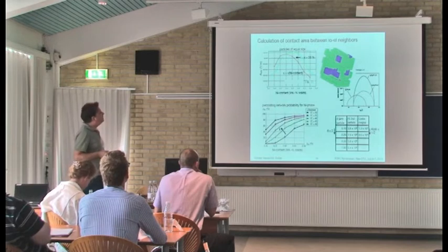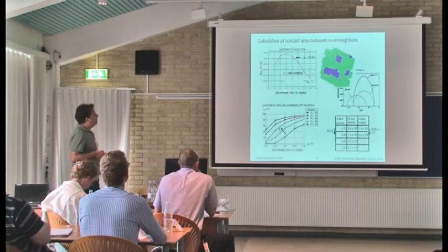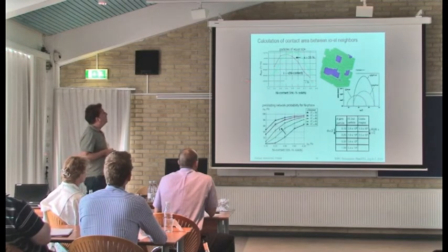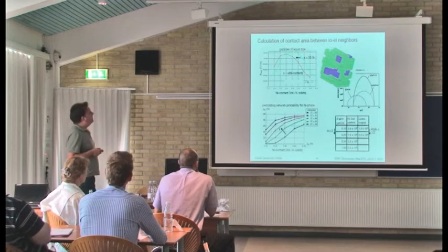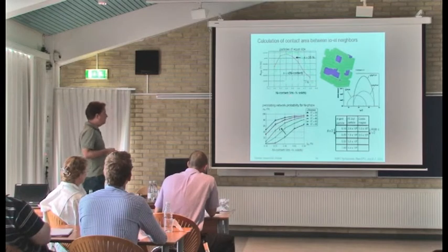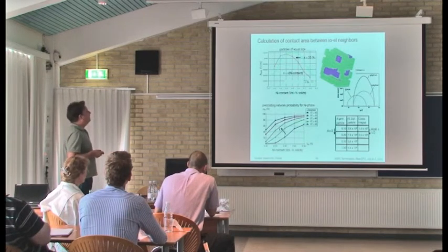But what is interesting, if you take into account that the porosity changes with nickel content, this has an effect on the interface area you calculate. So for equally sized particles, you get this bell-shaped curve, which is symmetric about a nickel content of 0.5 in volume percent solids. So when you now include the porosity change with the nickel content, this means that this curve shifts